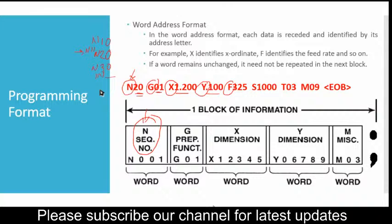Okay, now the second part is the preparatory function. If the number is preceded by G, G is a preparatory function. If the number is preceded by G, then it will operate the machine at that. Suppose let me explain the meaning of G01. G01 stands for linear interpolation.